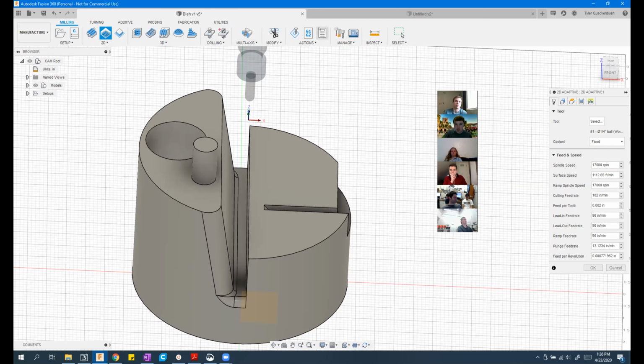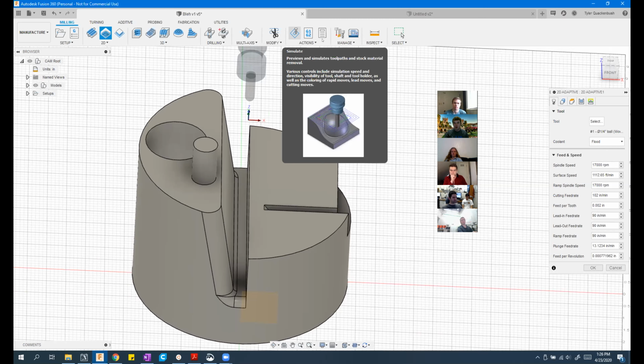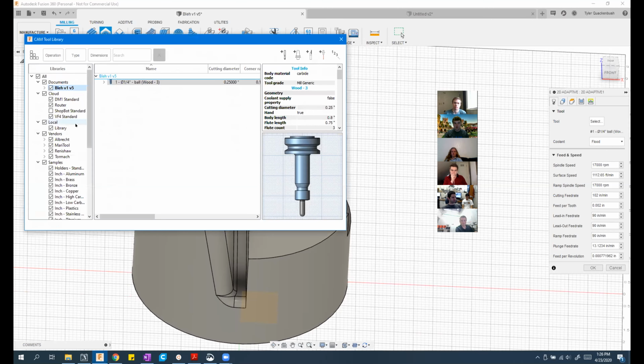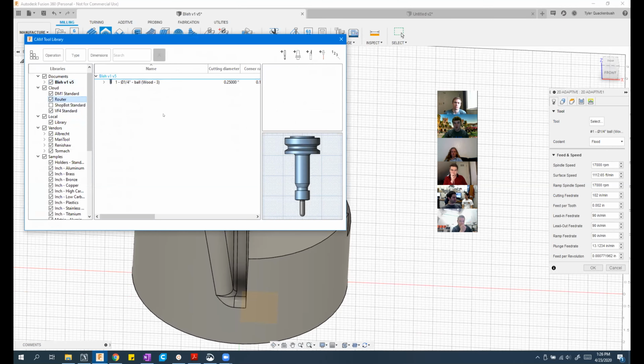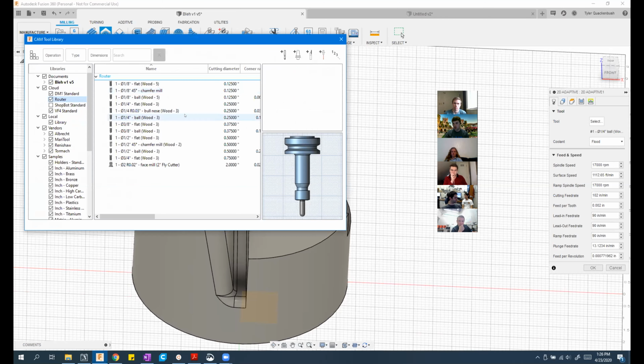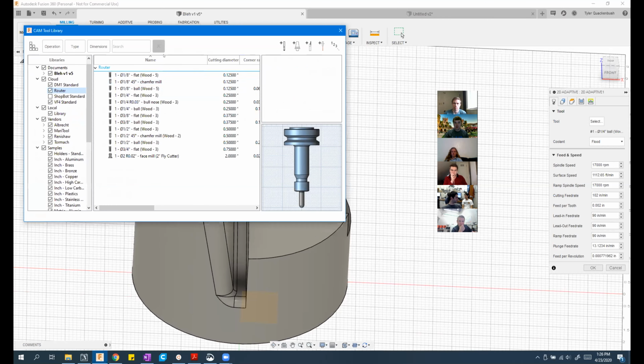Okay, so you guys are aware, the way we're gonna run it probably with the new CNC router is we're going to have some libraries that we create that we hand to students. And we're gonna say, okay, these are the 10 tools, or these are the 8 tools that are loaded in the Shop Saver right now, and here are feeds and speeds with them.